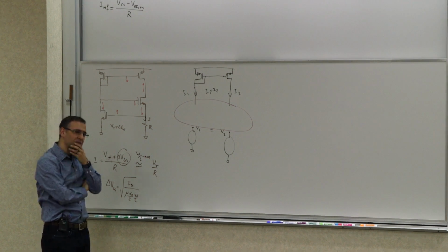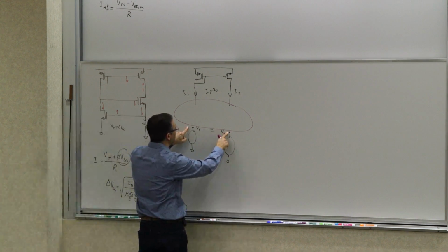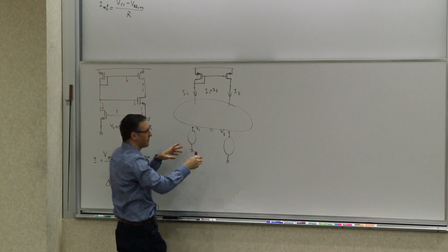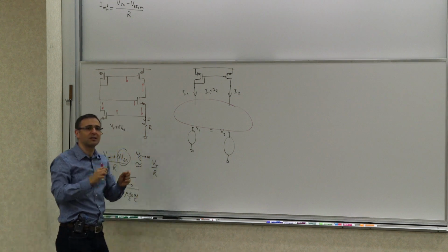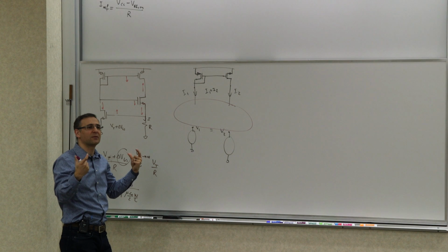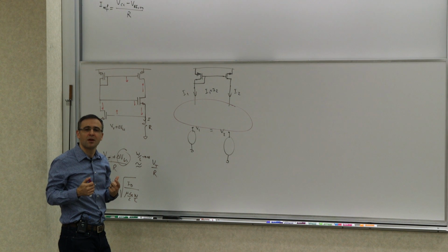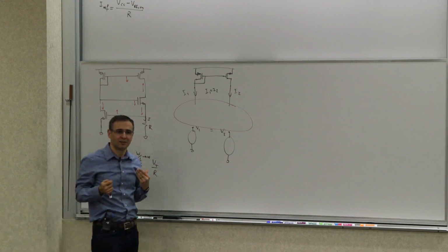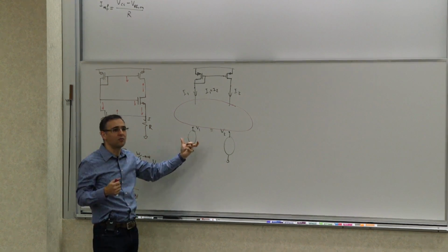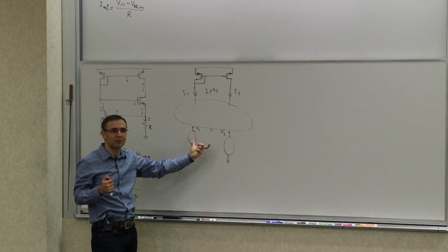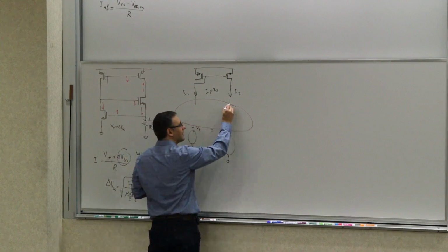So think about it this way. If you can make these two voltages derivatives of another voltage, derivative meaning derived from, not the calculus derivative, if they're generated off of a different voltage, if they have a fixed relationship with a given third voltage, then you can force them to be equal, right? Let's say they are both lower than that voltage by 1 volt. If I have a third voltage, and these two are both 1 volt below that voltage, then they would be forced to be equal, right? Can you think of a simple way of using transistors to achieve that?